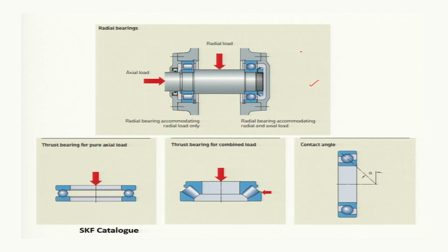We have seen in the case of a gear drive, when the drive is through a spur gear, then there is only a radial force and a transmitted force, and these two forces become a resultant force, and that will be a resultant radial force. So, in the case of a spur gear, there will be only radial force. So, this force will be there, and so you have to choose the bearing accordingly. You may choose a rolling element bearing or a roller bearing depending on the amount of load which is acting on the shaft.